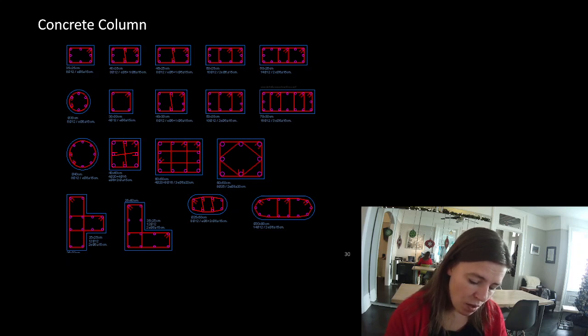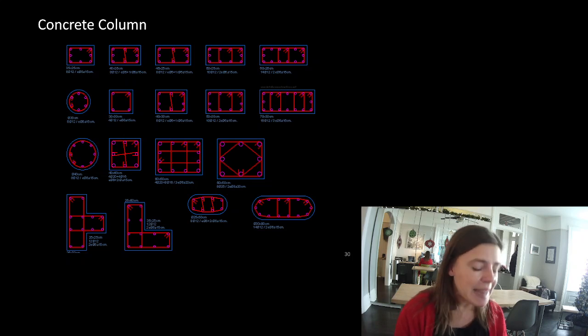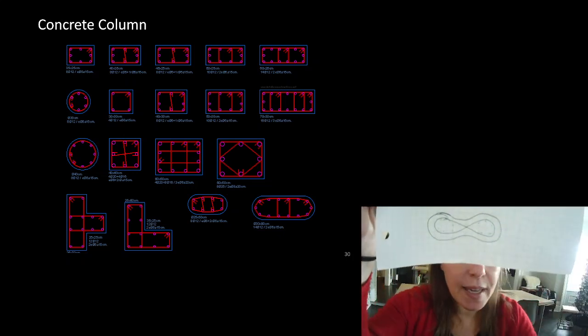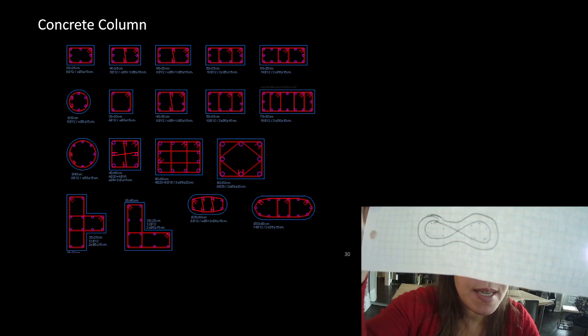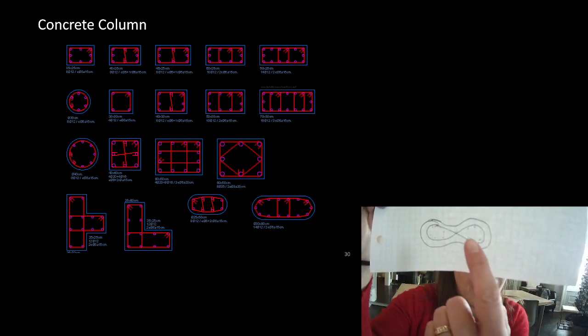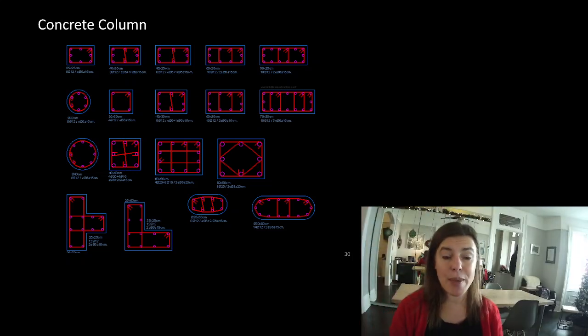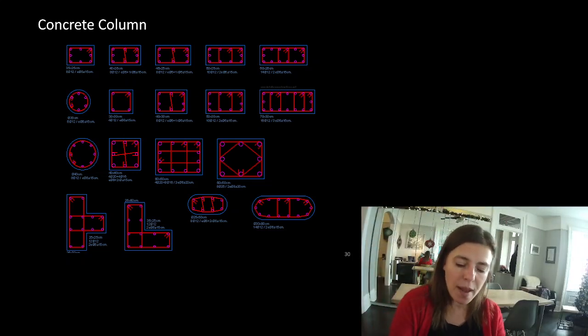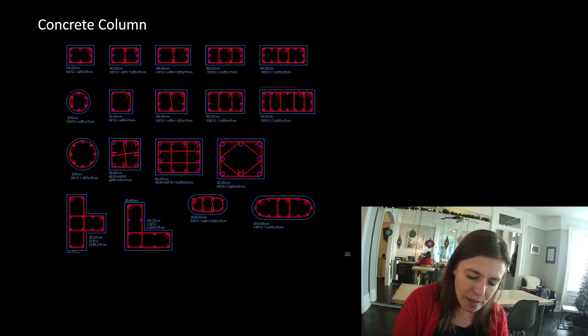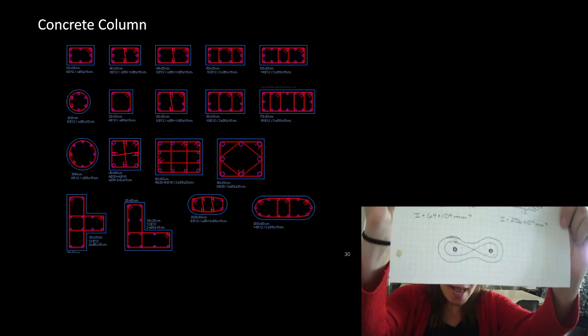They're peanut-shaped columns. On Sisters. Yeah, it was Sisters, right? Not Integral House. They did all the steel ones in Integral and Sisters. And they crossed those ties over the peanuts, right? I think so, yeah. My memory is they were almost figure-8 ties. So for that, they had peanut-shaped concrete columns. And so you can see here, they had to contain all of that, but also tie the two halves of the peanuts together. I didn't do the final design for that, but my canopy then had elements that were cored down in between that.